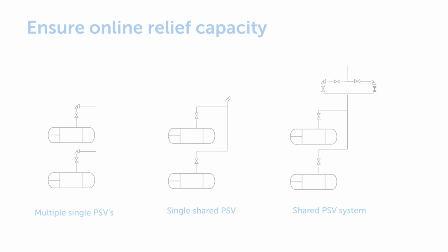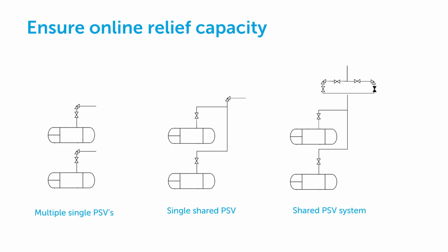Heat exchangers are connected to pressure relief capacity. Each exchanger might have its own PSV. Multiple exchangers may share a single relief valve or a system of parallel relief valves. The same goes for rupture disc overpressure protection used instead of pressure safety valves.